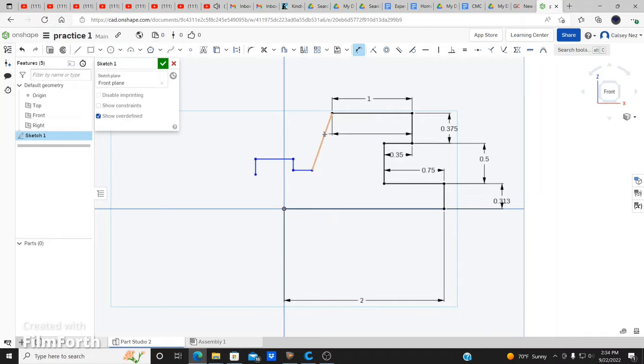Select this line right here on the angle, so that way it'll activate a degree. And from the degree, it's going to be 105.00. Enter. That's it. So again, you select these 2 lines only. That's it. Don't worry about the corner. Don't worry about anything else. Just the lines itself, because that way it'll activate that line specifically.